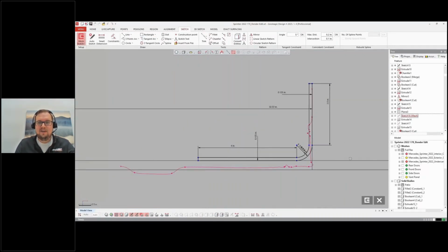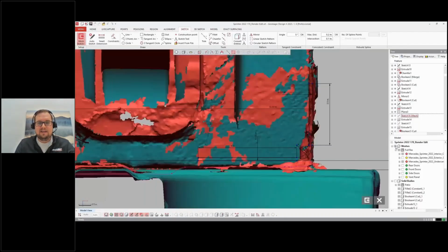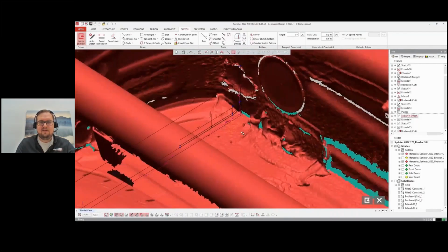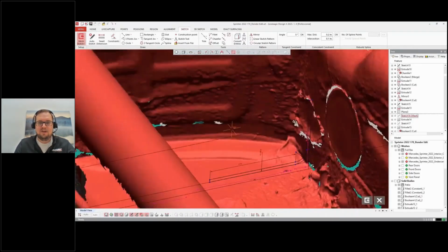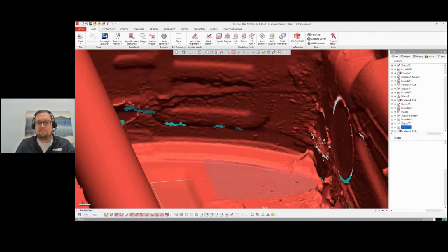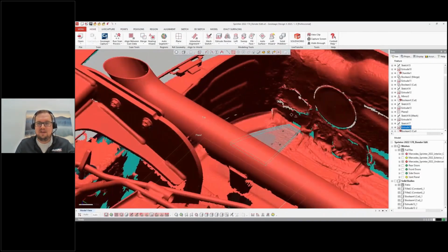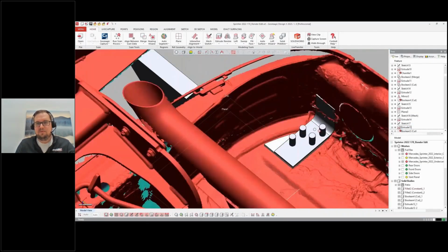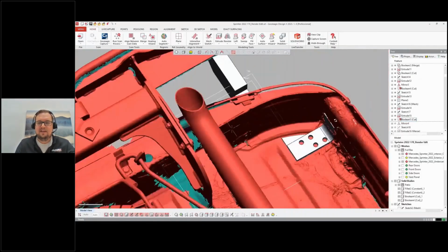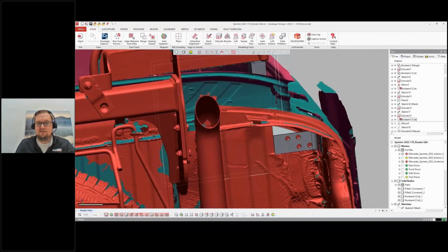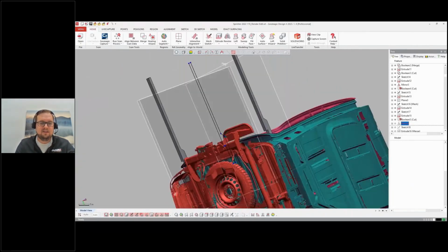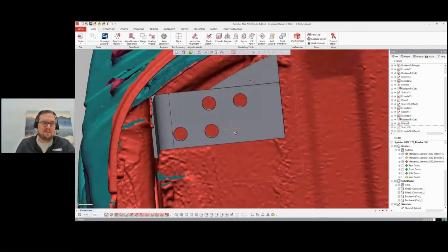I can also go ahead and create a support bracket off the side here, spaced off with my spacer. From the side here, I can see there's some anti-corrosion undercoating that will need to be scraped away in order for me to mount that bracket. But I can tell it's not going to interfere with my CAD model. So once the bracket's in place, whether it gets welded or bolted into place, I know I have the room to do that. And I know I'm right up against the frame of the vehicle, or in this case, the external body line. So each side I can just double check.